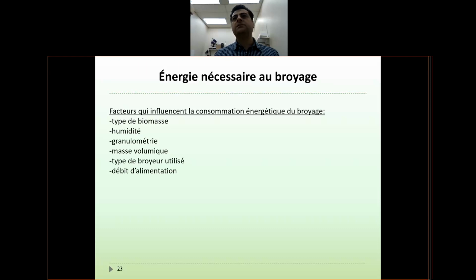So you see inside the dryer, you see these tubes. This is interesting because this is a special dryer for indirect drying of biomass. So these are the tubes inside which air or steam can flow, but biomass is in between in the shell of the dryer. So there is a kind of indirect exchange of heat in these kind of rotary drums.